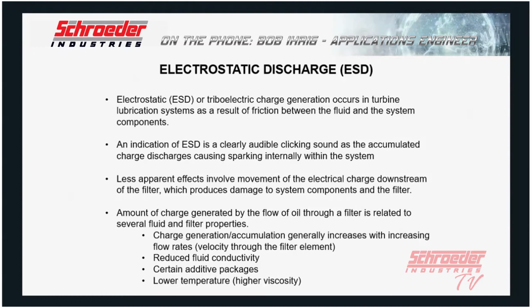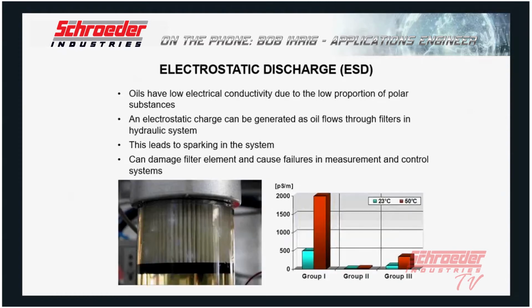Typically, electrostatic discharge, or a triboelectric charge, generally occurs, and it's not specific to a turbine lubrication system, but that's just an example. It's a result of the friction between the fluid and the system components. In some cases, there are other more technical and scientific ways that it occurs, which we can share with you privately or in another conversation.